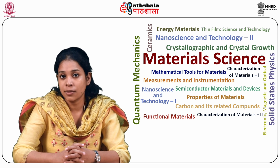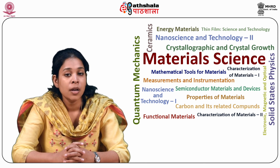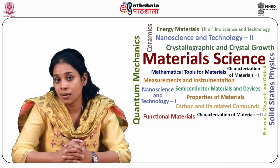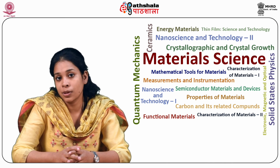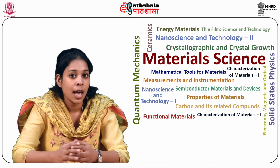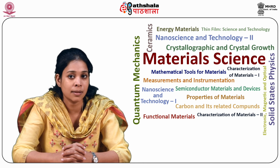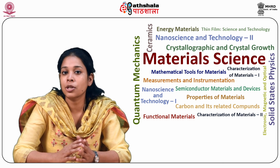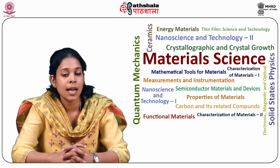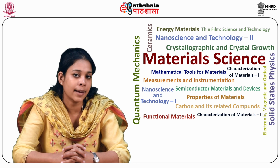Zirconia. The main raw material for zirconia is zircon, that is ZrSiO4, which is found in beach sands. The details of zirconia we have also discussed in this module. Pure zirconia, that is ZrO2, has a cubic fluorite structure, which we have learned, at temperatures above 2370 degrees Celsius. On cooling, it changes to tetragonal phase at 2370 degrees Celsius and then to monoclinic phase at about 1100 degrees Celsius, which can be easily understood from the phase diagrams.